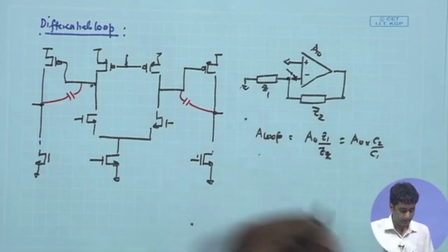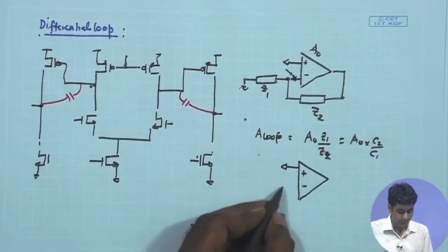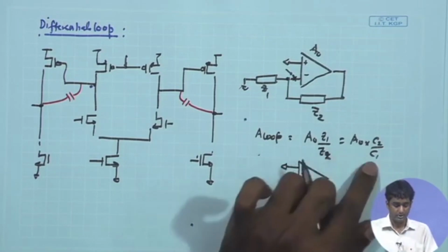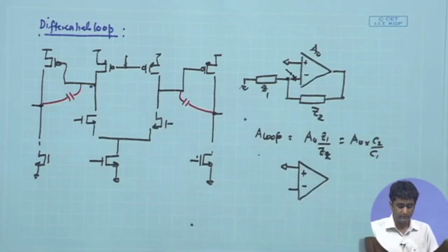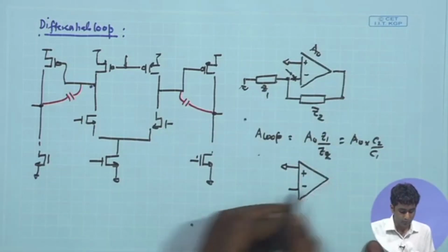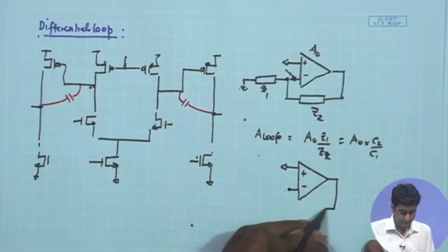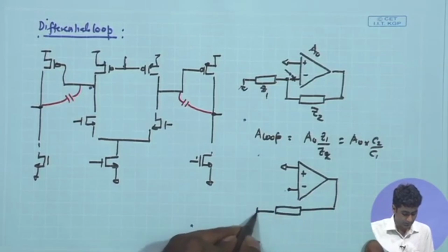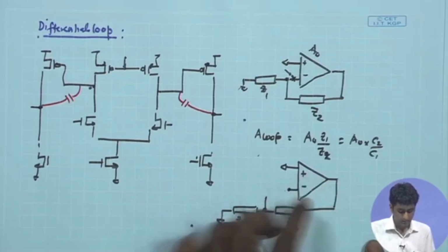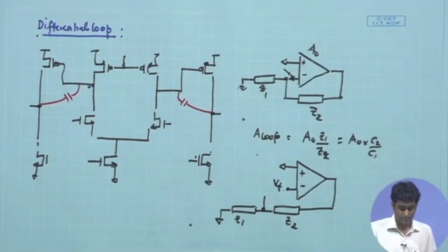So, we can open the loop and see that first of all you have to confirm that yes, the loop gain is same as what we expected using the shunt topology that we arrived at. So, we had discussed the overall feedback topology that we are having, and we arrived at the loop gain. So, if you are opening the loop at this particular point at the negative input terminal of the op amp, and then looking at the final voltage signal coming over here, we need to be sure that yes, your feedback signal over here, the overall transfer function between the Vt and the signal over here is also similar to what we achieved earlier.